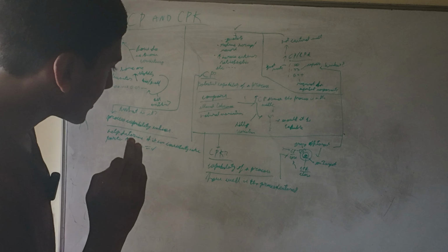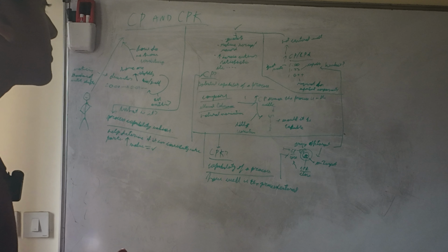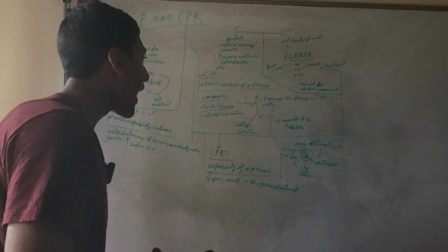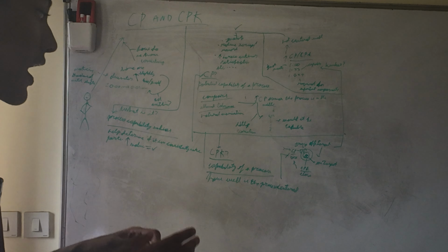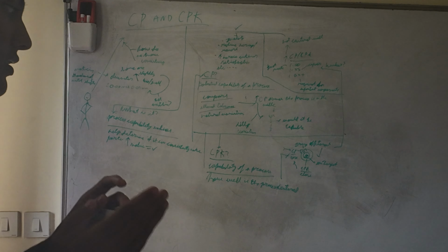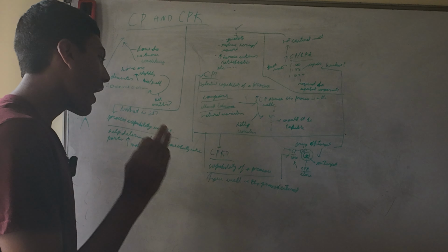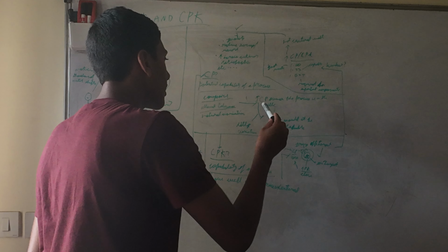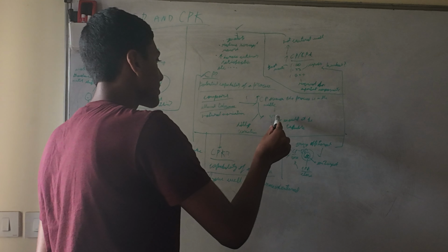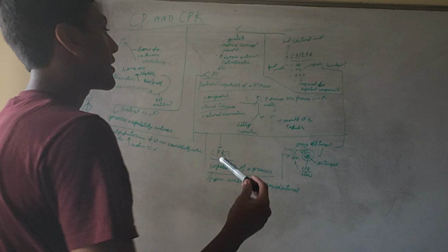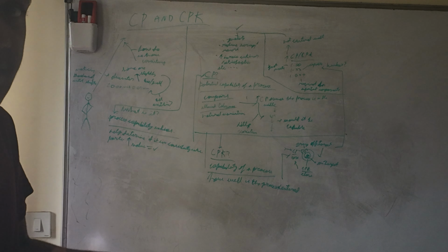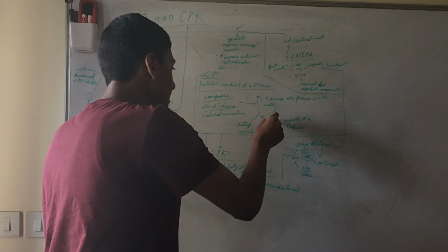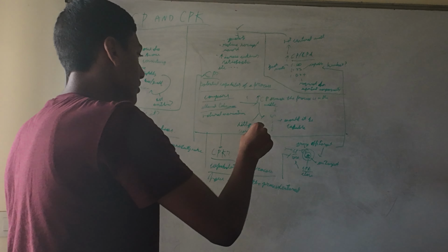But what about CPK? Unlike CP, which measures the potential capability, CPK measures the actual capability of the process itself. It basically asks the question, how well is the process centered? Instead of CP, which assumes it's centered perfectly and asks if it is capable, CPK checks whether it can actually hit the center.